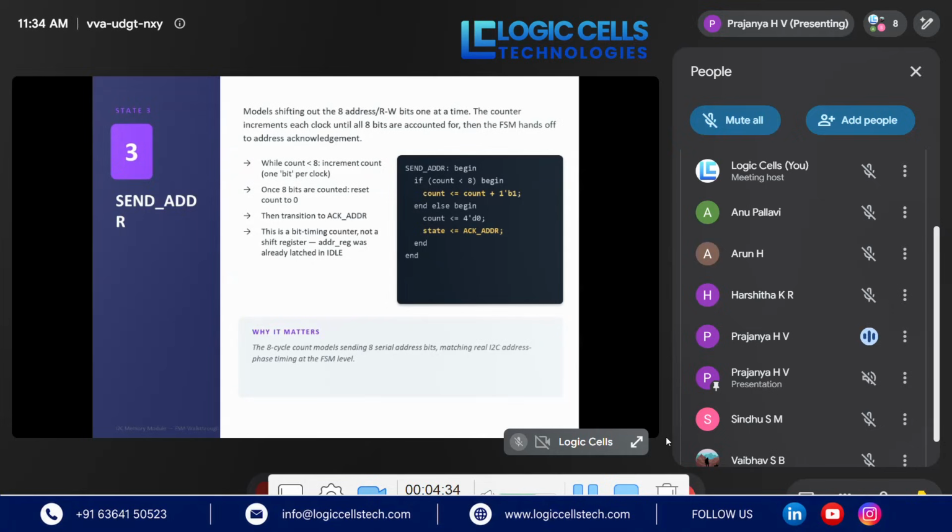For I2C, the address information contains the 7-bit slave memory address and 1 bit of read or write information. So they have declared a 7-bit address, and the counter keeps tracking the 8 bits being transferred.